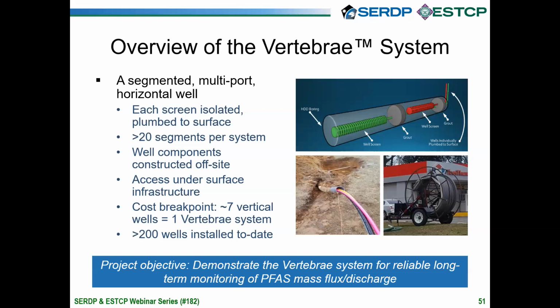You do have a setback distance. So, it varies on condition, but let's say your setback requirement is 1 to 5. And I think probably in most settings you can be more aggressive, but the math is easy. If you want to go 20 feet deep, you need to step back 100 feet, 20 times 5. So that's sort of the depth limitation.